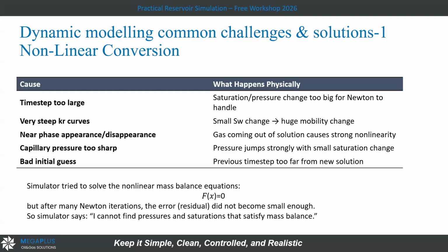I call it nonlinear in the mathematical sense: nonlinear means a variable to the power of 2, or two variables multiplied by each other, so it's called a nonlinear function. The mass equation, or the continuity equation, when converted to numerical form, is a nonlinear function, so these nonlinear functions will appear a lot in the simulation. If you have this error when you make the run, go through all of this and smooth your model.